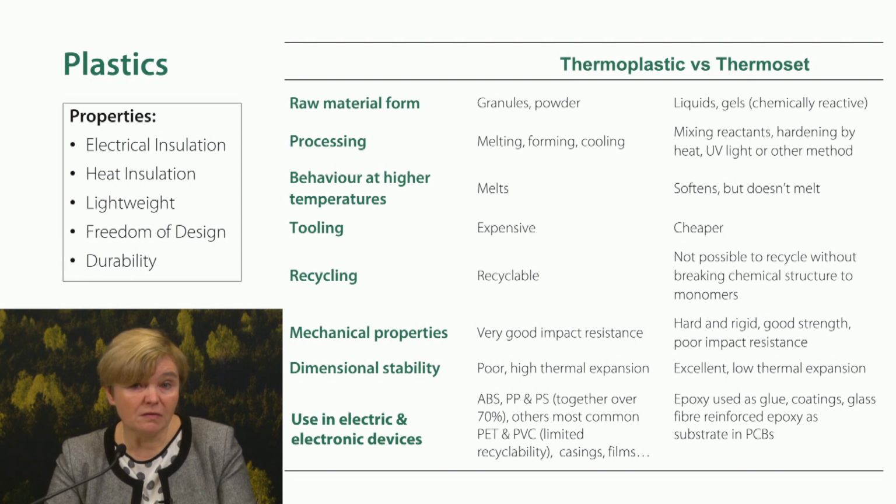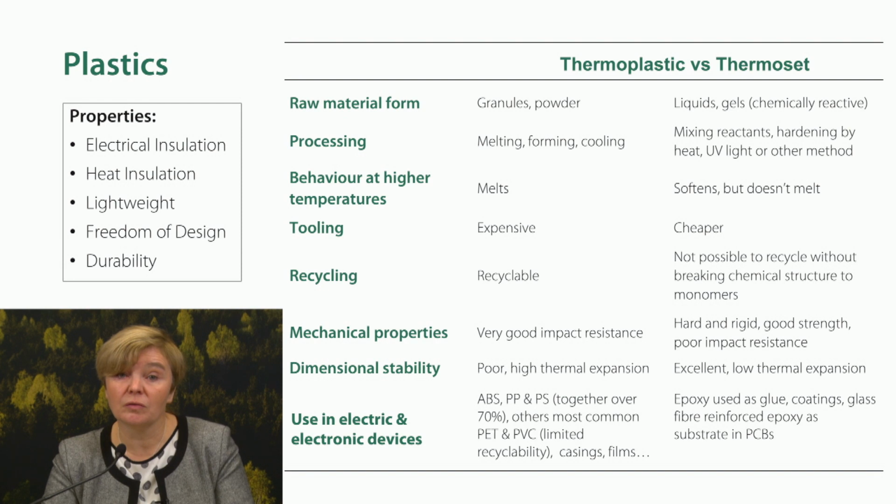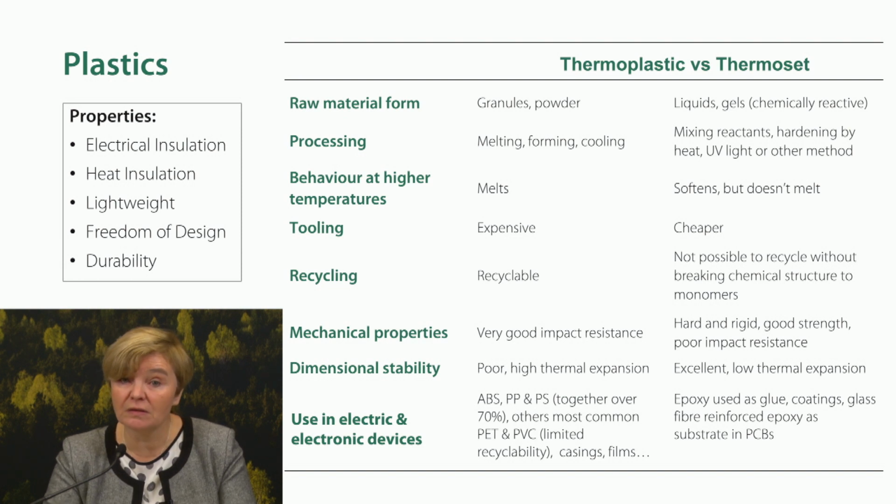We have also PVC. I need to mark that PVC is actually very difficult to recycle, as this is a material which has chlorine inside. PVC is polyvinyl chloride, which during melting can start to decompose, and during decomposition hydrochloric acid is formed. So it means that your processing instruments can start to corrode, and then recycling of PVC is not really what any recycler wants to do.